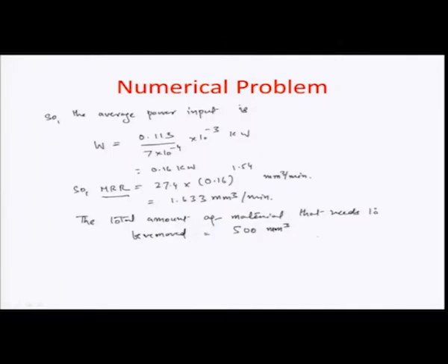The dimensions of the hole, the thickness of the sheet, etc., are all provided in the question, and so therefore the time required to complete this machining operation comes out to be equal to 500 by 1.633, that is 306 minutes.